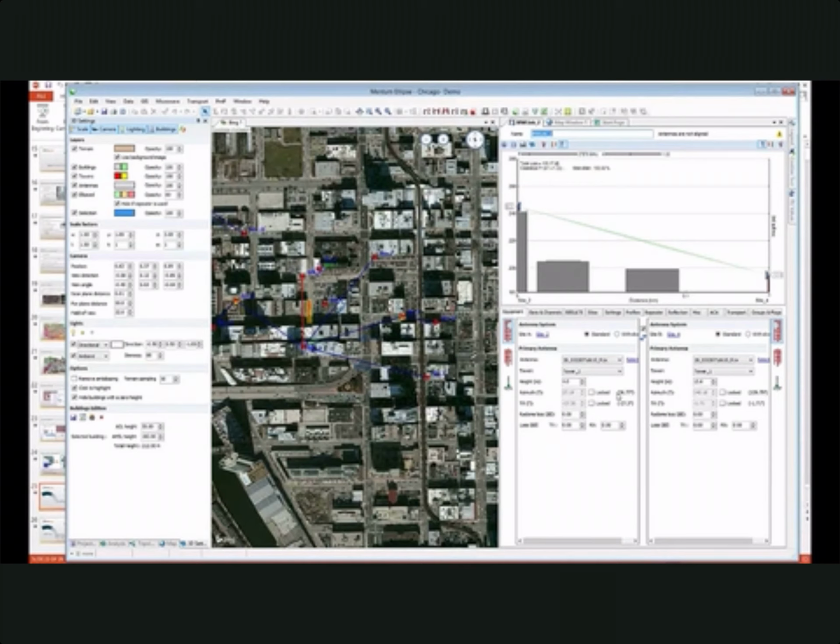Okay, I think that we will go to the next question. It says that for the long line of sight there will be a signal loss in addition to the free space loss. But does that mean the need to use lower fade margins? If you have an additional loss, you can add any additional loss, but you must have a fade margin still.